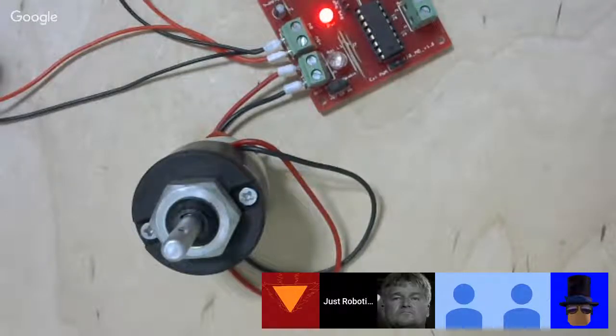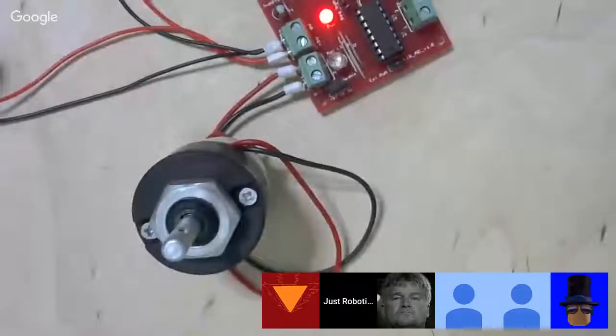So that is where we bring in pulse width modulation, where we give pulses to the motor in such a way that it is not visible, but effectively it reduces the speed of the motor, or reduces the brightness of the LED, or reduces the extent to which the motor could rotate or the LED could glow. Right? Let's start doing it. Let's see how the program is written.